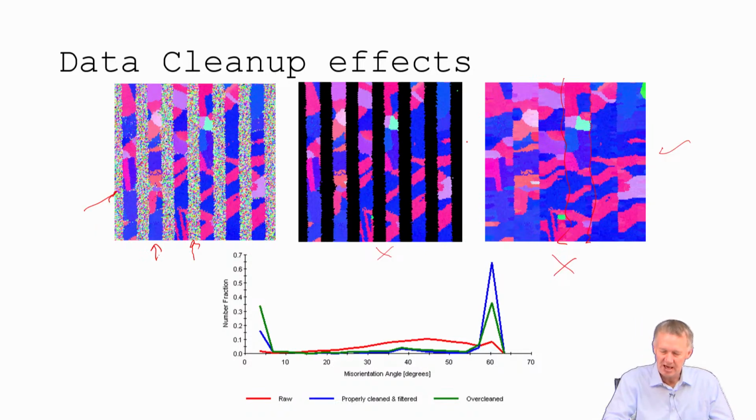So in this case, we have this black region where nothing's defined. And so these grains here can just grow straight across, which you see what they've done here. Although that green is kind of interesting because you see that tiny little green point there? Somehow that was left in as a grain definition for that. So that green one started to dilate and started to grow before the blue one came over and impinged upon it.